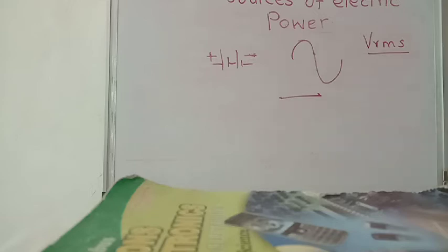It is called as armature. So when this shaft is rotated at some specific speed by some external device, then the coil on the shaft also rotates. And with the same speed, this coil is kept in a powerful magnet or in a powerful magnetic field, and which cuts the magnetic flux and thus